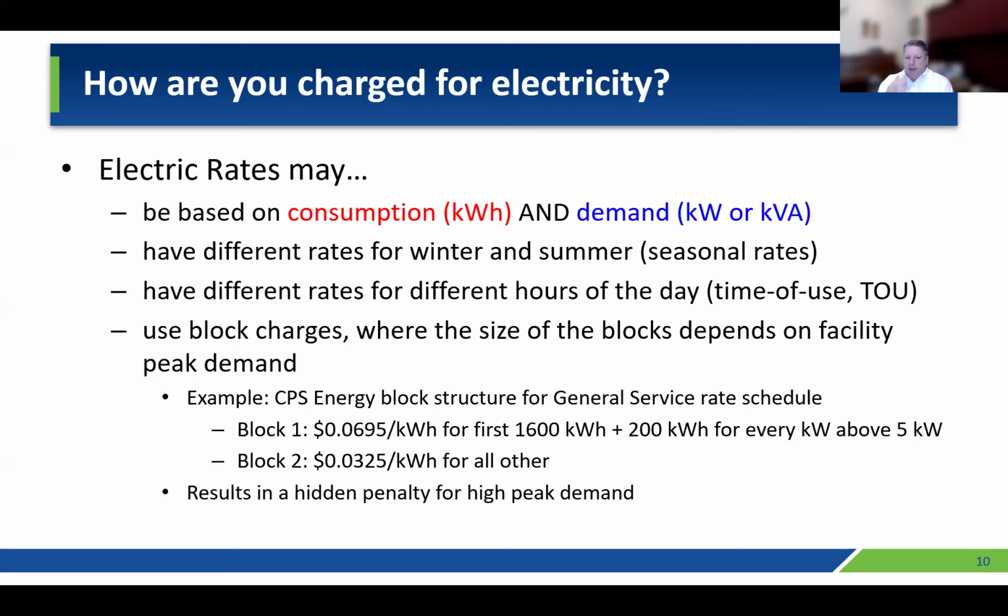Now, we should note here that in the Gulf Coast region in particular, electric rates may be dependent on a lot of things. You may be charged, of course, based on your kilowatt hours and your peak kilowatts for the month, but those rates may differ depending on the season. They may differ depending on the hour of the day, particularly on our coasts in California and New York. They have looked at time of use, where your rates may change with each hour of the day.